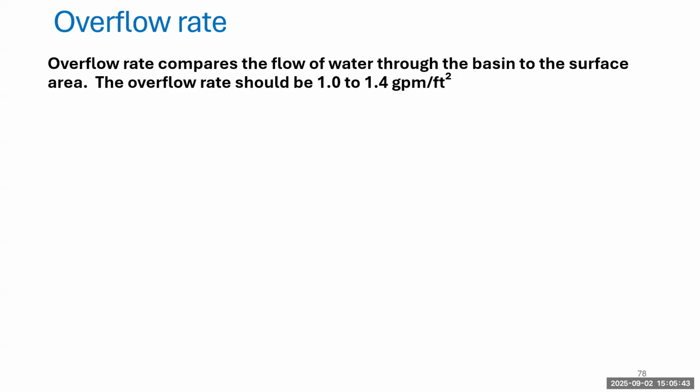You could express this in cubic feet per minute as well, and you could reduce it down to a velocity of particles or water flow in feet per second as well. But for now, just know that the overflow rate is directly related to this time allowed for particles to settle. So we're going to look at an example here